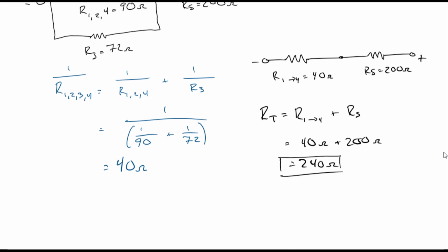You're just constantly looking for what's directly in series or what's directly in parallel. And every once in a while you can combine, because you've got two different portions that are in series, so you can do it in one step. But what you're creating is an equivalent model, slowly going through this and analyzing what the combination of components would be, with their oppositions either added in parallel or added in series, depending on how they're connected. So I'm just going to leave this one at resistance total.